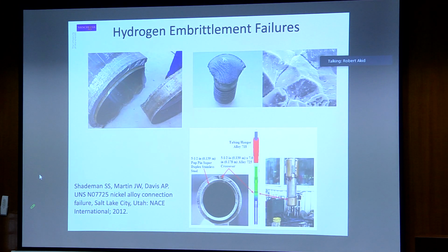I'm aware of time, so I'll quickly move on to hydrogen embrittlement, which is just a brittle fracture mode due to the effects of adsorbed hydrogen, which can be as a result of prior electroplating, of cathodic protection, or just the difference between the corrosion potential between two different materials.